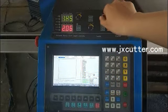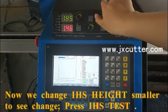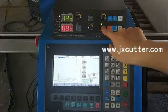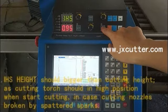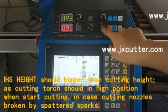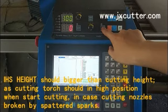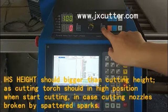Now we change IHS height smaller to see change. Press IHS test. IHS height should be bigger than cutting height, as cutting torch should be in high position when start cutting, in case cutting nozzles broken by spattered sparks.